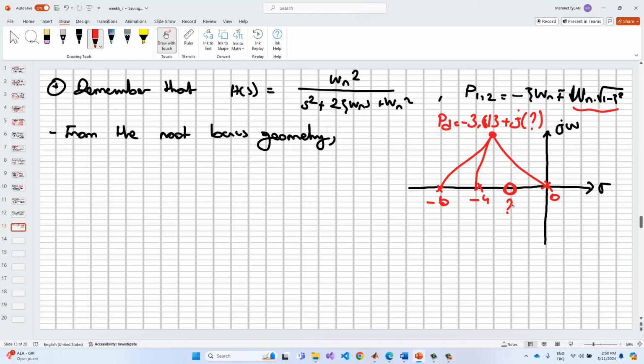in here, okay? And so from the geometry we know that we have theta 3 and theta 2 and theta 1, okay? And so this theta 1 is equal to 120.26 degrees. Just using the geometry you can easily calculate these things, but in MATLAB you don't need to use that. But if you want to design any root locus or the PD controller in here, we need to define the geometrical relation in here, just like this one, okay?